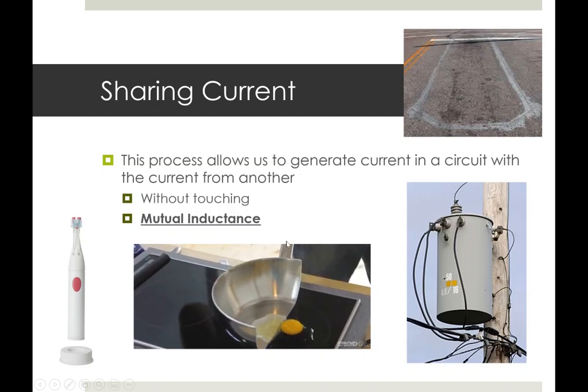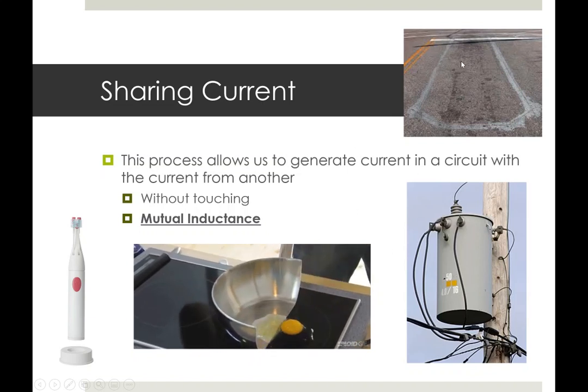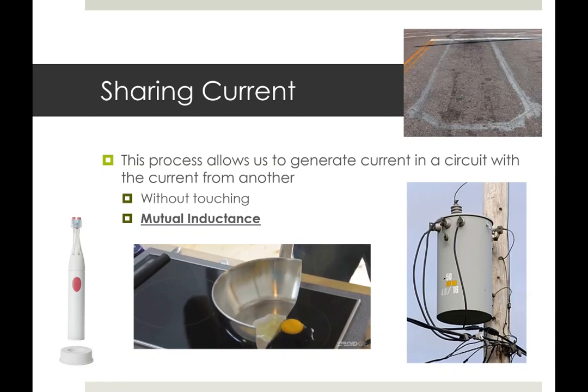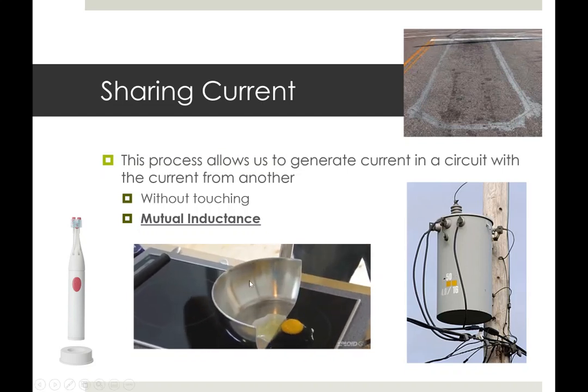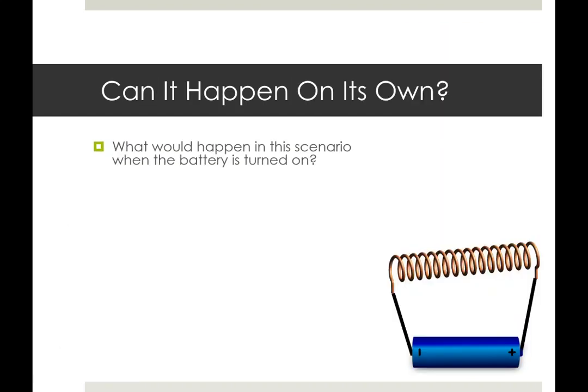to interact with. And we'll see that it measures that as inductance, and what's happening is every time your car drives over it, it is noticing that change in inductance. It is not a pressure plate, it is purely an example of what's going on here with this circuit behavior. So we call this mutual inductance, of sharing from one to the other, but could this happen on its own?